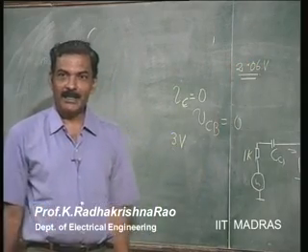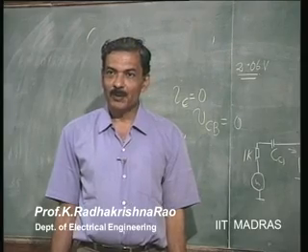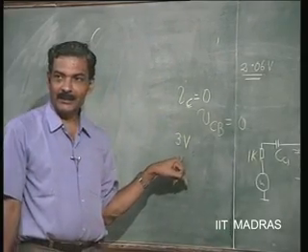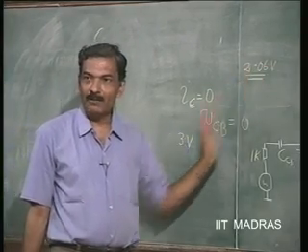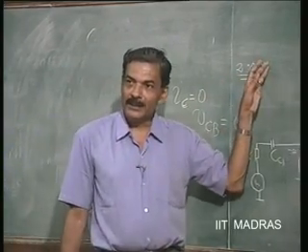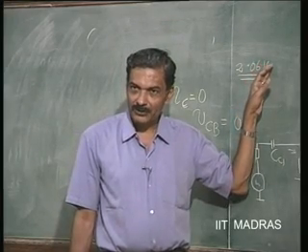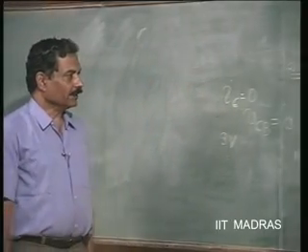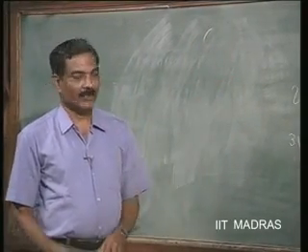So, this symmetric signal swing here is how much? 2.06 on either side, because here it can go as much as 3 volts. So, it can easily go to 2.06. So, the lower of these two will set the limit for symmetric swing at the output. So, with this, the complete discussion of the common emitter amplifier is over.